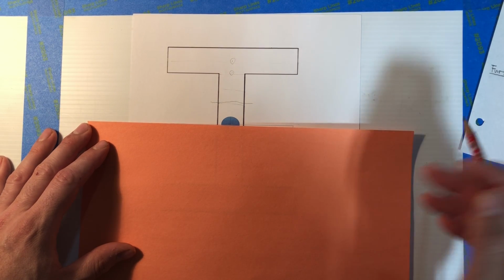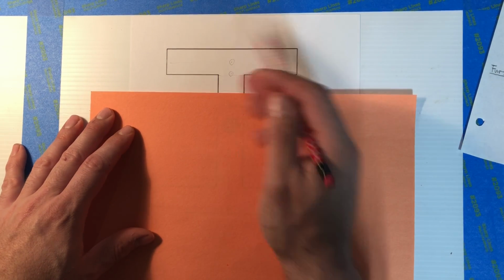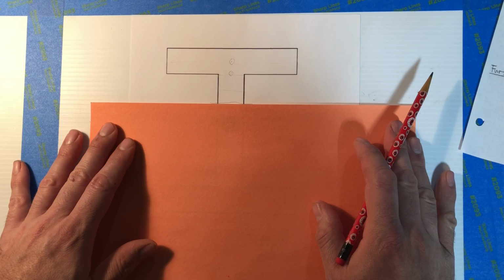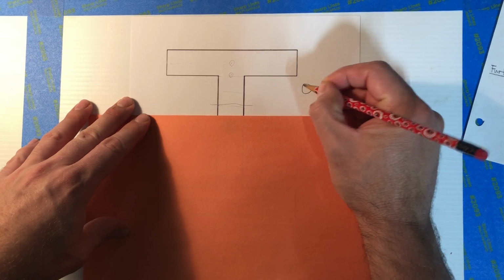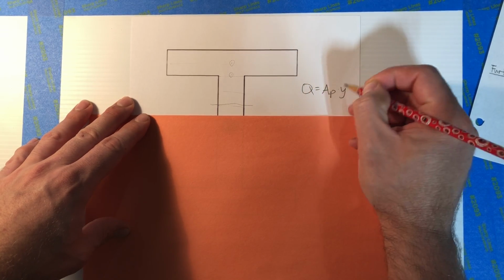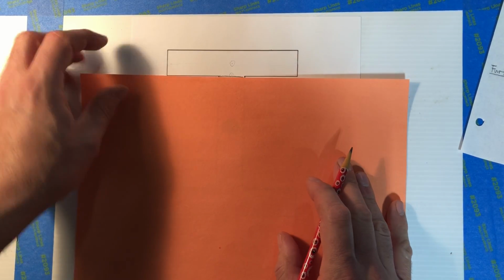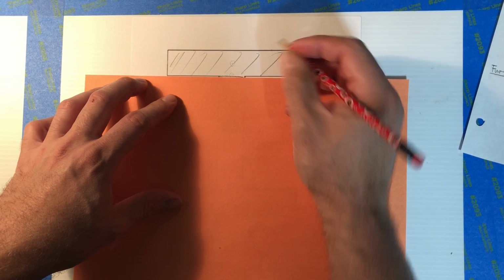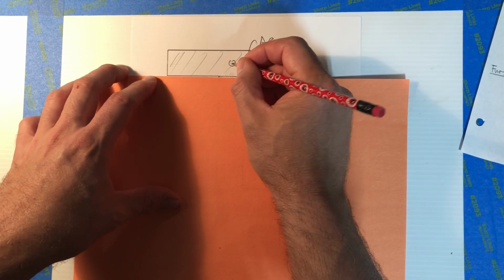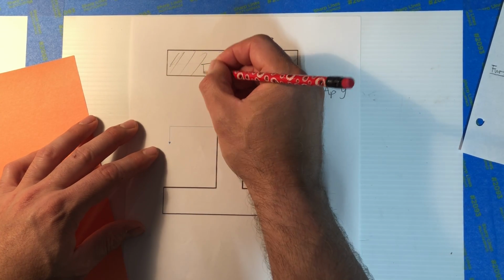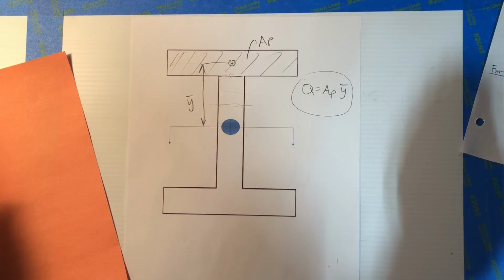So when we're trying to find the shear, that Q value is wherever you want to find it, cover up the rest of the beam. And sometimes it's a one-piece area. Sometimes it's a two-piece area, right? And basically it's just a multiplication of that A_P times Y bar. So once again, say I wanted to find the shear stress right here, okay? Cover that up. A_P is this whole thing, the area, okay? And the centroid of this new region is there. The distance between here and the overall centroid, that's Y bar. So that's my Q value, okay?